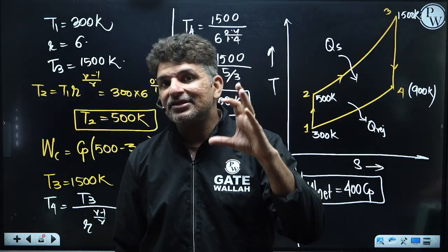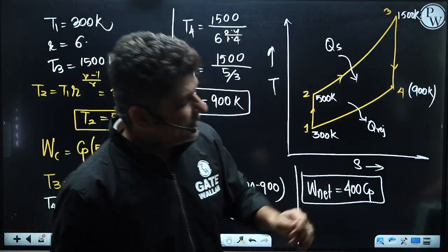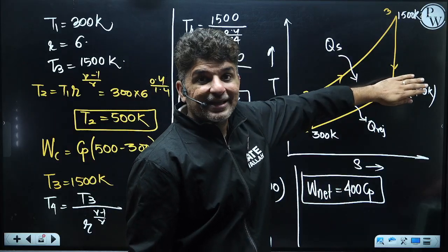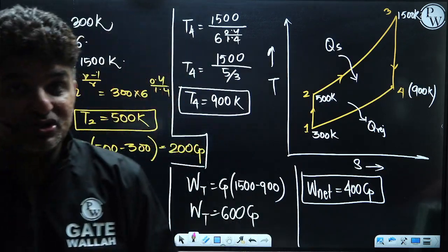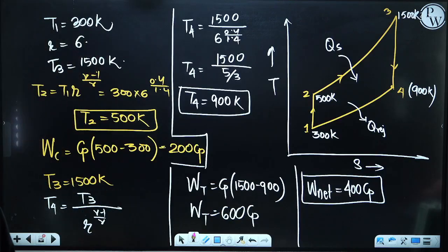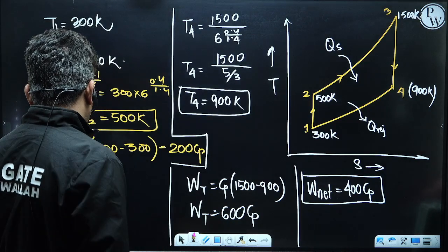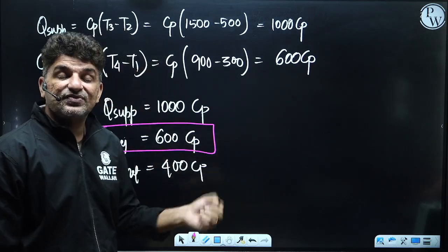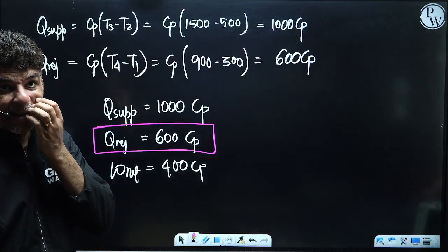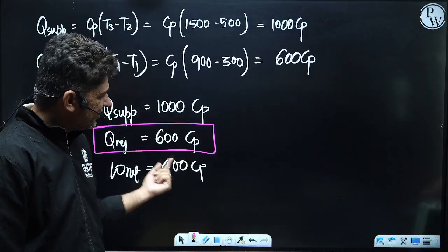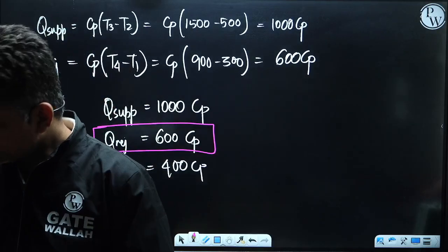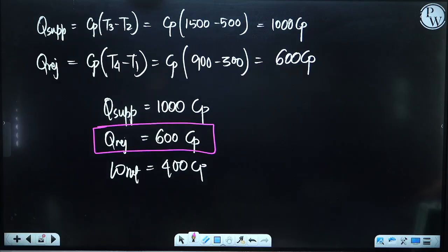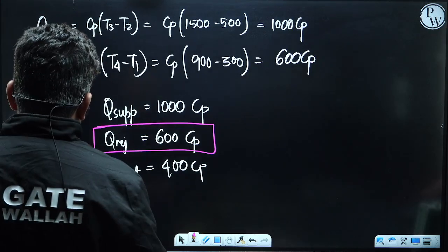The Brayton cycle is very inefficient because the gases which have expanded after the turbine are still at extremely high temperatures. These gases have an enormous amount of energy which you are not able to utilize, and that is why this cycle has very low efficiency. If somehow we can harness this energy, then our efficiency can be improved. So we will see how this energy can be harnessed.